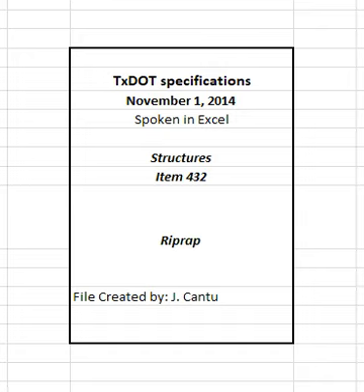1. Defined as that size such that 10% of the total riprap stone, by weight, is larger and 90% is smaller. 2. Defined as that size such that 50% of the total riprap stone, by weight, is larger and 50% is smaller. 3. Defined as that size such that 92% of the total riprap stone, by weight, is larger and 8% is smaller. The engineer may require in-place verification of the stone size.